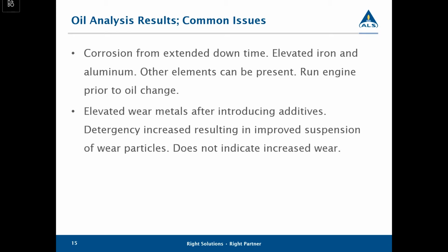Elevated wear metals when using additives, this is another thing that we've seen quite often where an additive such as CamGuard is added. And what happens is normally you have an increase in wear metals from that. And a lot of time it's due to the increased detergency of the oil itself once that additive is introduced to the system. And detergents, they're a good additive. They're really good for suspending particles so that they can be carried through the system, carried to a filter, and then when oil changes occur, that they can be taken out during that oil change.